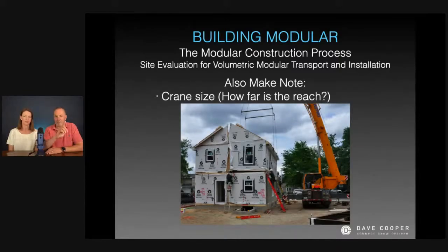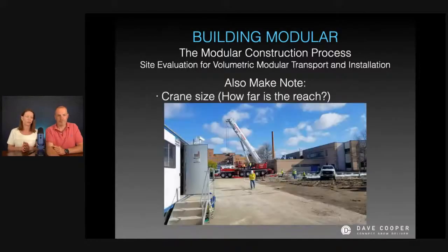Now, during this whole process, you have to think about staging. Where are the modules? Where are all 4 of those pieces sitting so you can get this set up and staged properly? Exactly. And also, what type of foundation is being used here? Because that will determine how close you can get to the home. If this is a precast concrete foundation, like Superior Walls, you cannot get as close to the home as you can with a poured concrete foundation. Not at all.